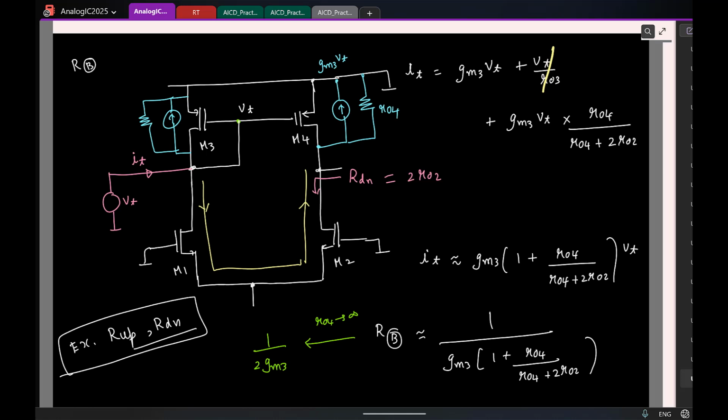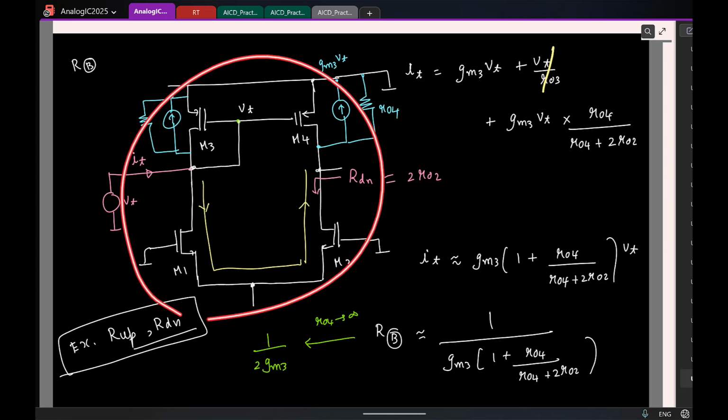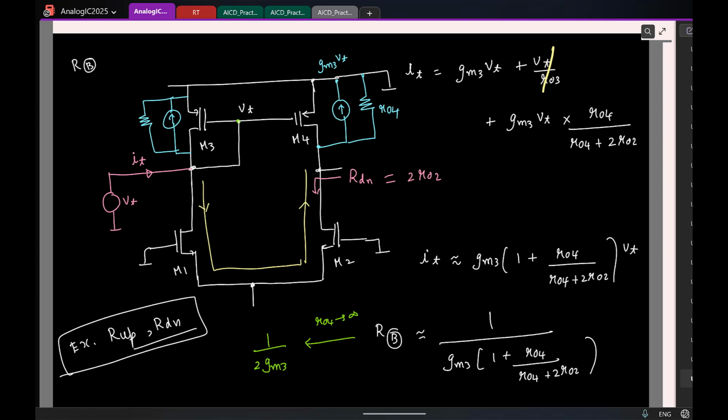So now we have done a bunch of small signal calculations on this 5 transistor OTA, and we also know what is the gain of this. So let us say you design this for a very, very large gain. And why do you want to make amplifiers with infinitely large gain? To be used in negative feedback.